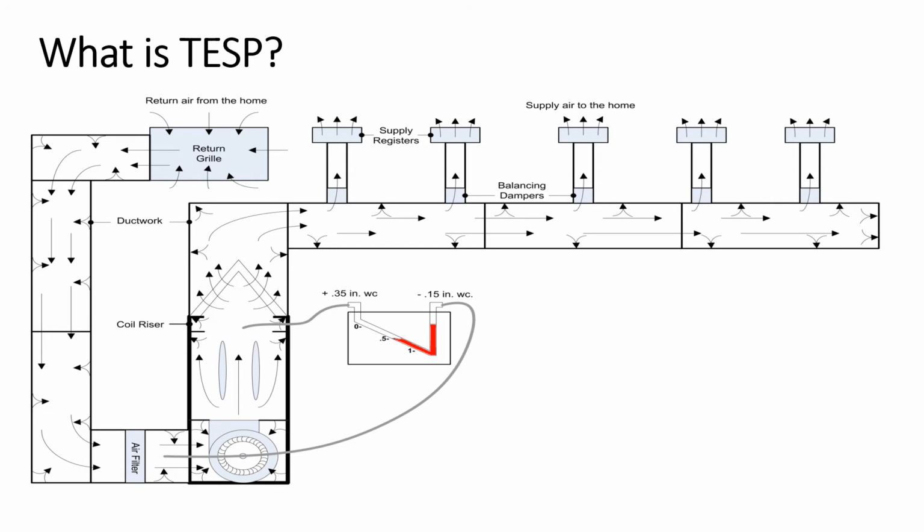This example here is a gas furnace, so our cooling coil, or our DX coil if you will, is going to be external to that cabinet. Now if I had an air handler or maybe a package unit, this coil would be internal within the cabinet of my equipment. It would not be considered in my total external static pressure.